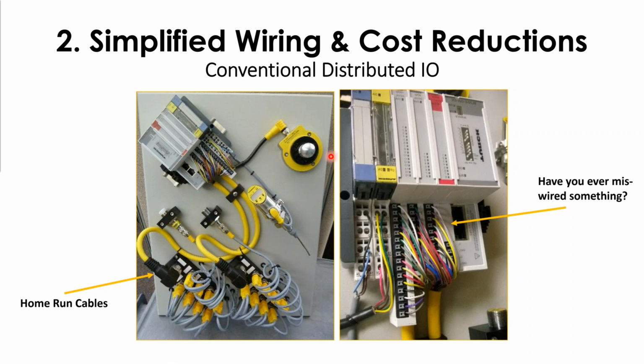So you might recognize this is a contactless encoder for a 0 to 360 degree position. This is a temperature transmitter with a 4 to 20 milliamp output. And these are traditional multi-port bricks, kind of like this on the camera. You've got up to 16 discrete I/O points and a multi-pin cable coming back, so you can have a pin for each device. This is something pretty common.